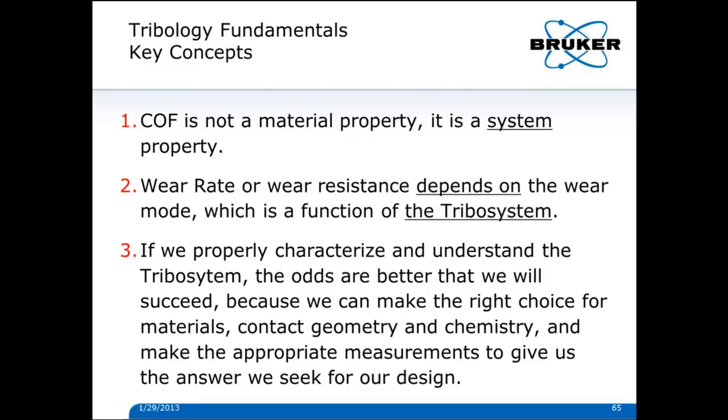We're only measuring two things, applied normal force and frictional force, but you have to have the system correct. The wear rate, or wear resistance, again, depends on the wear mode, which is a function of the Tribo system. So we need to get that Tribo system defined properly. Finally, if we properly characterize and understand the Tribo system, the odds are much better that we will succeed. So we can make the right choice for materials, contact geometry, and chemistry, and make the appropriate measurements to give us the answers we seek for our design.